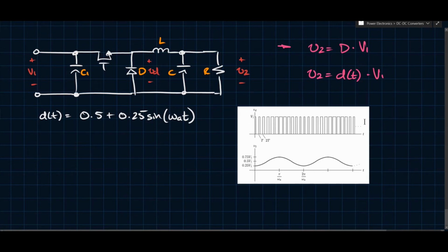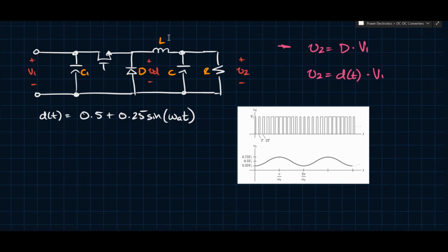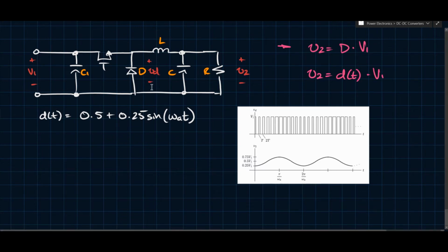And obviously the higher the switching frequency, the higher these harmonics will be, and the easier they are to filter with this LC pair. So the advantage of high frequency PWM is that the unwanted harmonics all end up being at higher frequencies, so they're easier to filter, right? So we see that based on, again, DC-DC converters and relatively straightforward stuff that we've seen in the past, through fairly straightforward circuits like the buck converter, which is a very common circuit, just by varying the duty cycle.